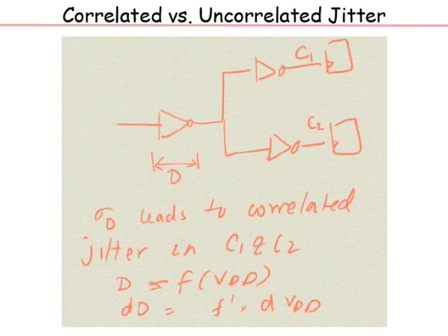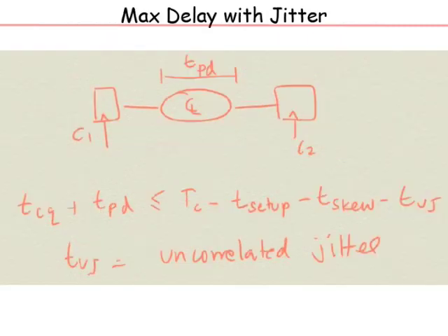If they're going in opposite directions, the capacitance is more. So that could also lead to fluctuations in the delay. All these factors make it very complex to precisely get a number during simulation. So usually, based on experience and some simulations, some conservative numbers are put for these parameters.